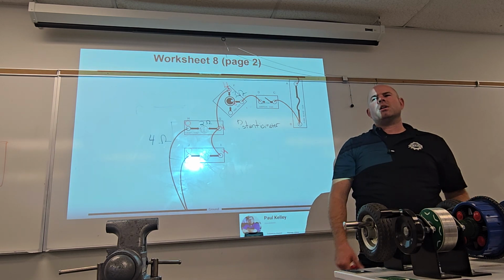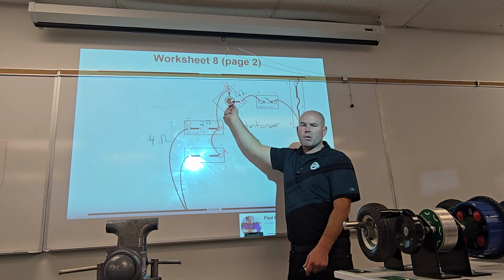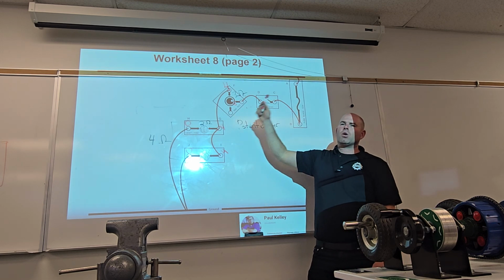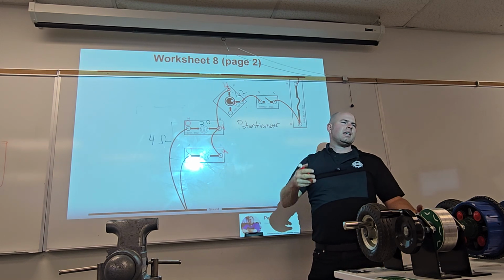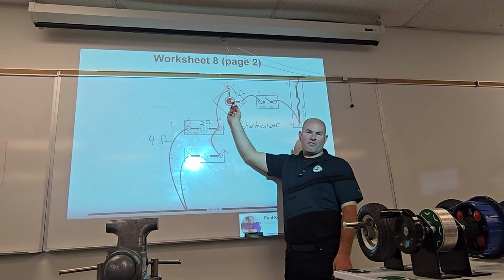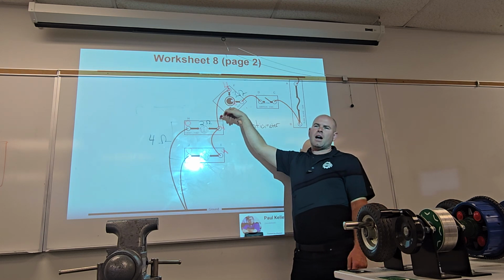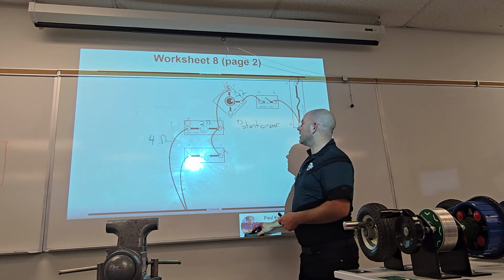You're like, these lights are too bright, just make them dim. Cool, we could do that. We'll put a potentiometer in there, and the potentiometer will consume the voltage and make it into heat. And that tends to be the failure point, by the way. These tend to get hot and fail with their carbon pile or whatever they're using.